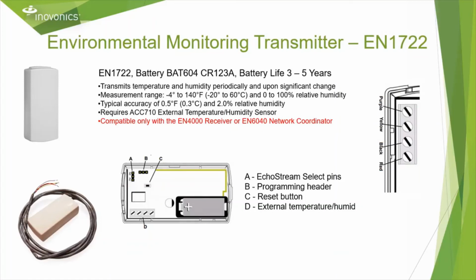The EN1722 requires the ACC 710 external temperature humidity sensor. It transmits back to its head end periodically and upon significant change. This sensor can detect temperature between -4 to 140 degrees Fahrenheit and 0 to 100% relative humidity. It has an accuracy of 0.5 degrees Fahrenheit and 2% humidity and has a 3 to 5 year battery life.